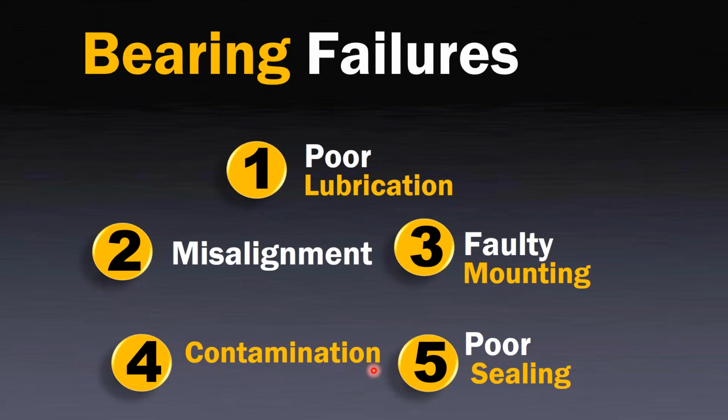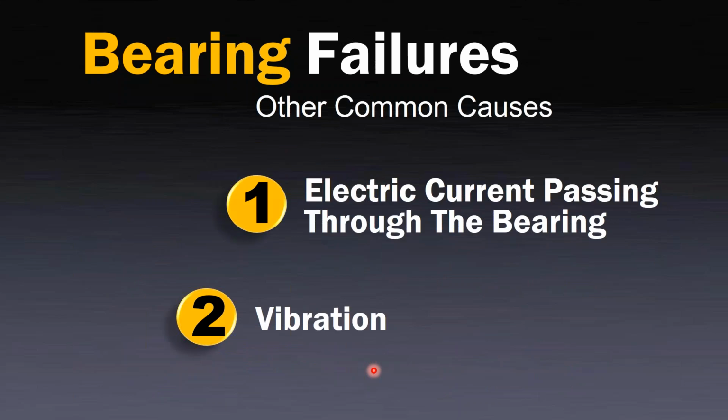You're probably aware of this, but bearing failures are due to things like poor lubrication, misalignment, faulty mounting, contamination, and poor sealing, but also due to electric current passing through the bearing and vibration.